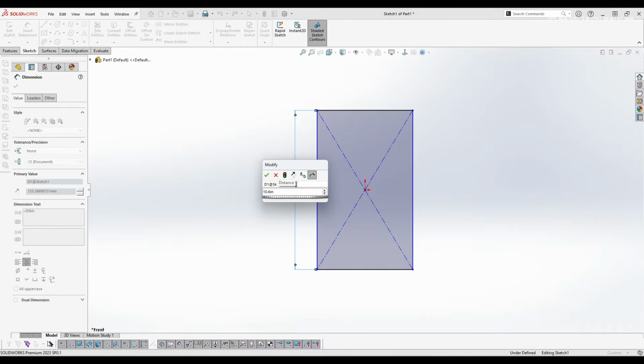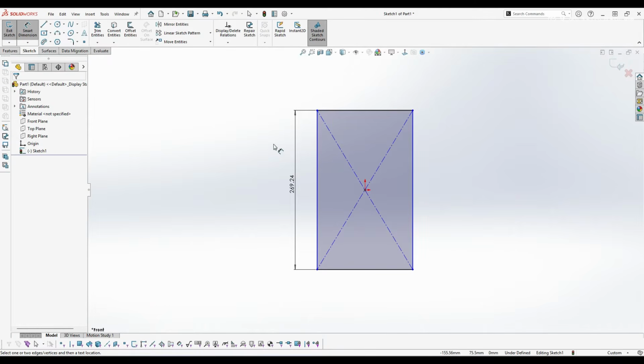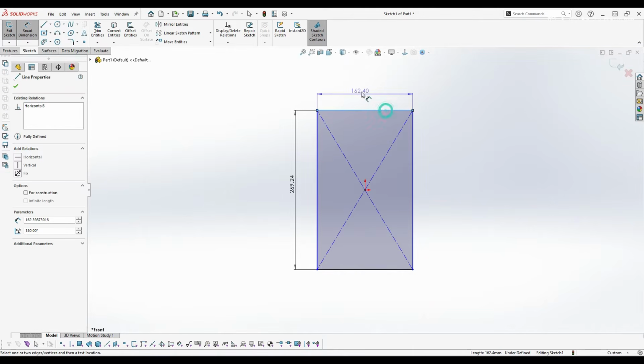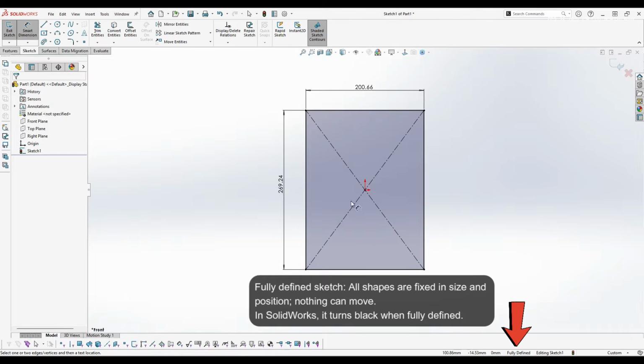By default, SolidWorks is in millimeter settings, and if you would like to have the dimension in inches, you can change it. You can change it from here, right? All the systems are mentioned over here. Next thing is the width of this plank. The width of plank is 7.9. Click the line and type 7.9 with IN for inches and press enter. So here we can see the sketch is fully defined.